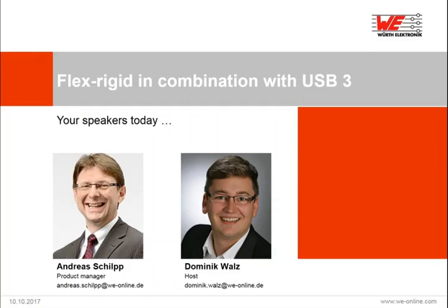So avoid long stubs, use standard through-hole vias wherever possible. But of course, finally, you are right, it's always preferable to have short lines. That's the reason that the USB driver normally is very close to the outline of the rigid part, and you can see it also in the second application I've shown you in the webinar.